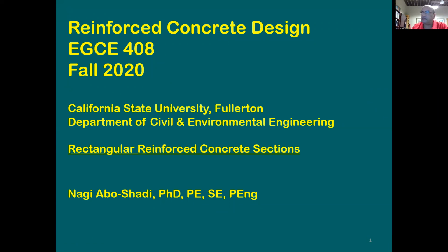So the previous slide said it's going to be about uncracked concrete section. Now this slide said it's going to be about cracked, which means we call it here reinforced concrete. We don't really call it cracked because all concrete are expected to crack. And the reinforcing is going to be mitigating the crack and control it. So I don't want to say cracked and uncracked. I'm going to say uncracked, I'm going to say reinforced concrete. Uncracked is going to be before the cracking point, before you reach the tensile stresses to f sub cr. And reinforcing, it means you have more moment than the cracking moment.